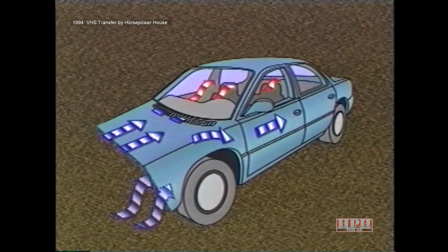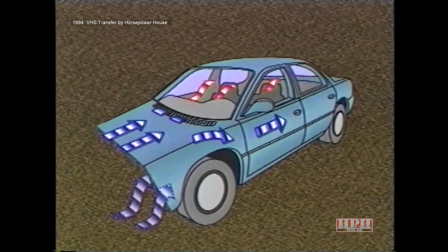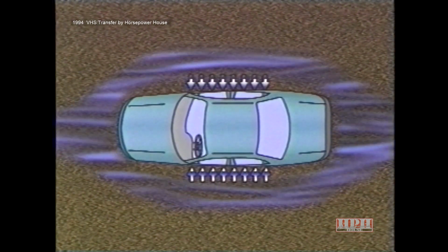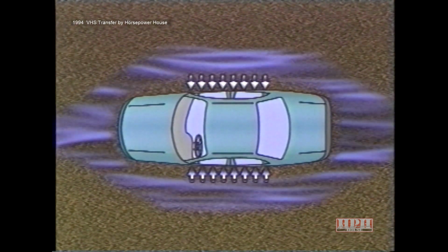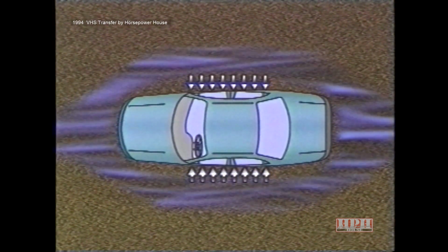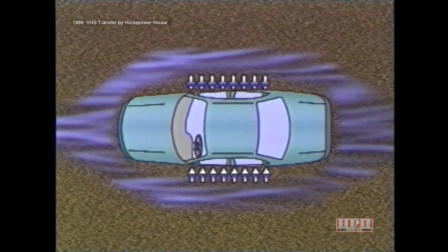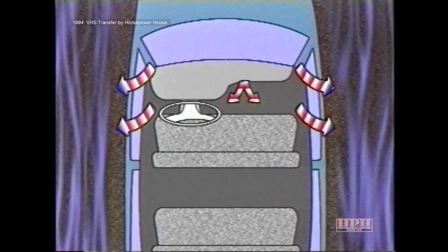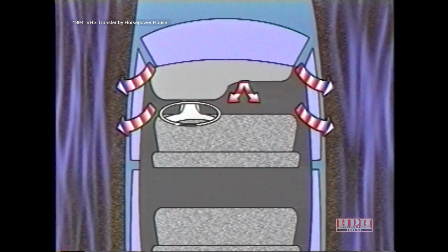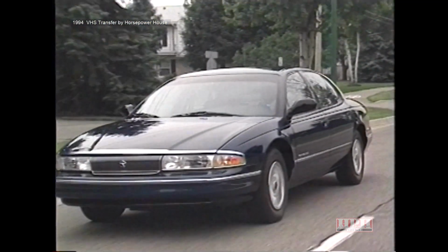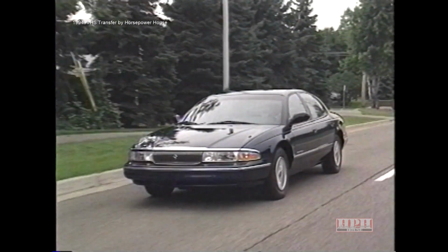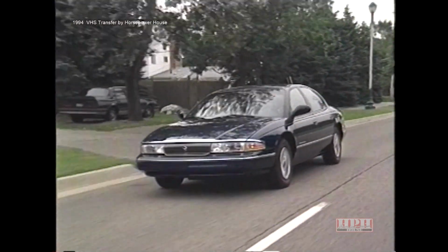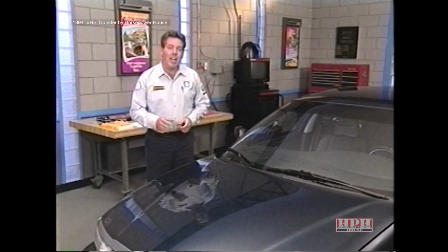The forward motion forces air into the vehicle, which causes pressure to build up in the interior. In addition, air flowing around the outside of the vehicle produces low pressure on the outside of the door glass, amplifying the effects of the interior pressure buildup. The difference between the high inside and low outside pressures may force the top of the door or door glass to lose contact with the weather strip, resulting in escaping air and wind noise. Air leaks caused by air escaping from the vehicle interior commonly make a hissing or roaring sound, much like a vacuum leak. In some cases,